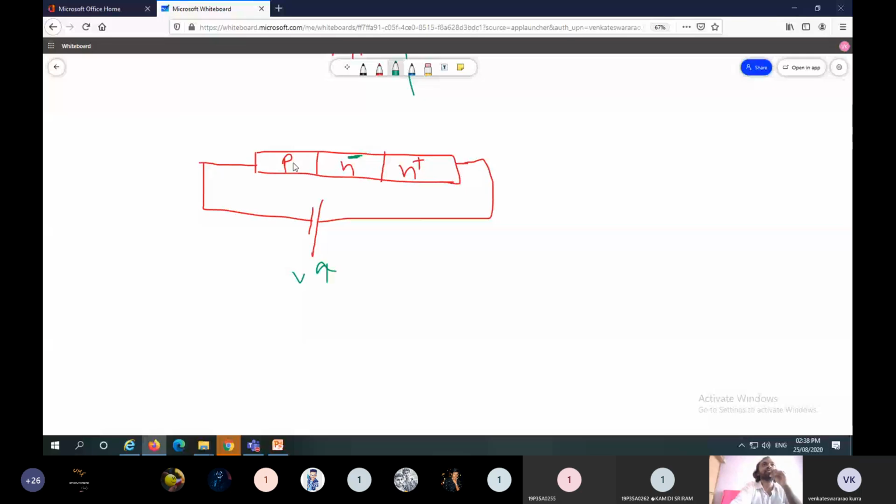So here it is the depletion layer and holes are moved like this. And some of the electrons moved like this. So it means majority of the depletion layer is diffused into the N minus layer. So here depletion layer width increases and charge density decreases. So it should be capable of blocking high voltage. So like this, by introducing this layer, we can satisfy both the conditions during on state and off state.